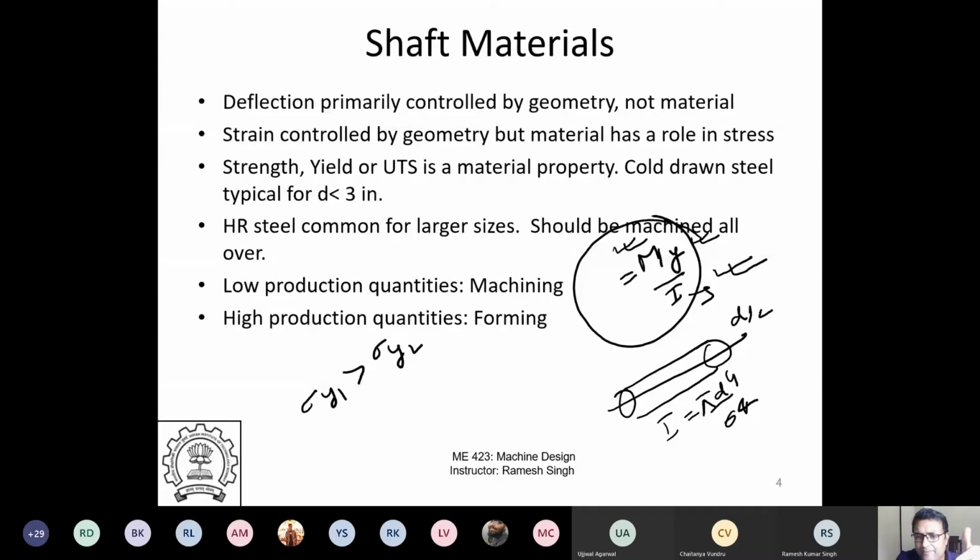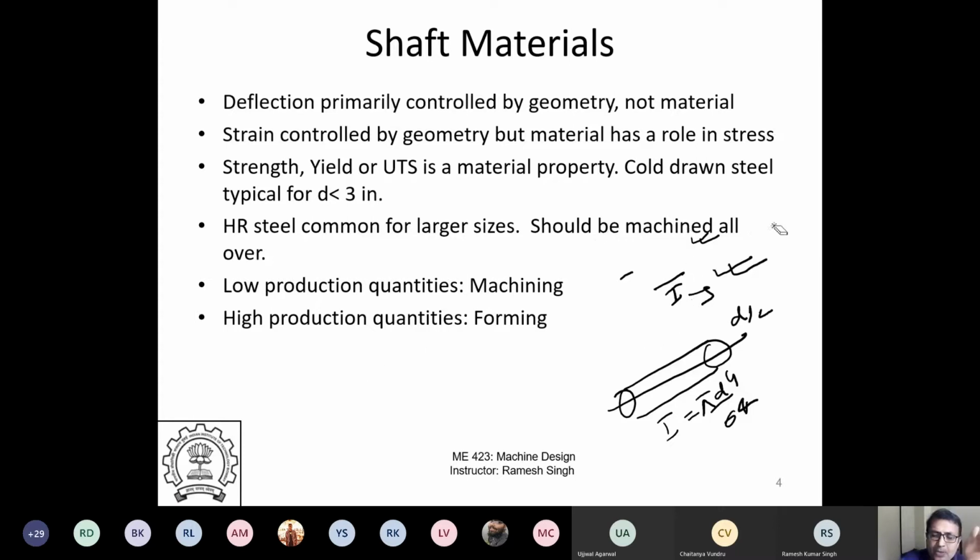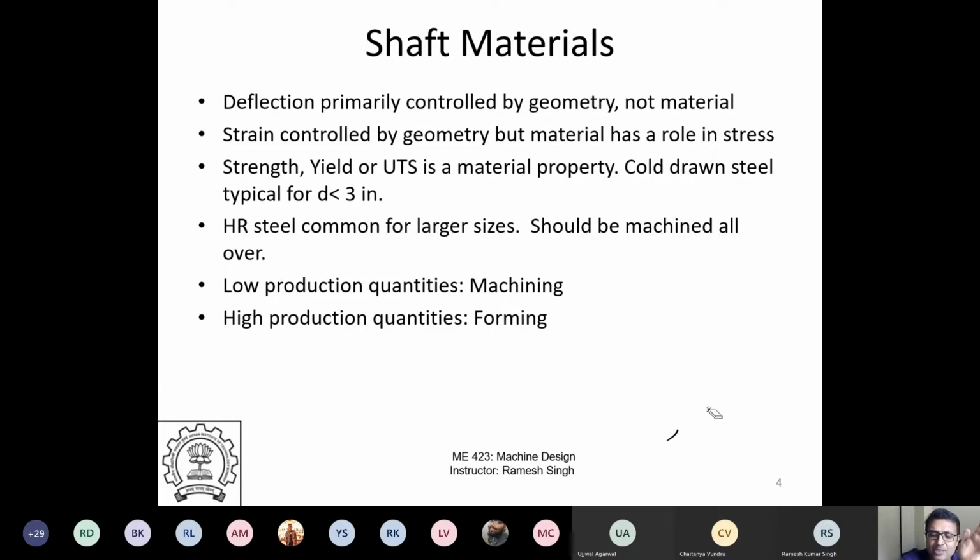But the problem is you're designing the thing, so you have to take yielding into account. You'd have some factor of safety, and what kind of moments you can transfer will be a function of where it yields. That's the limiting factor. It's a very correct answer, so you are right. Traditionally, strains are independent of material. Stresses are not, because epsilon is a geometric parameter, and sigma is E epsilon, and E is a material property. Everybody understands that, and it's a very good argument.